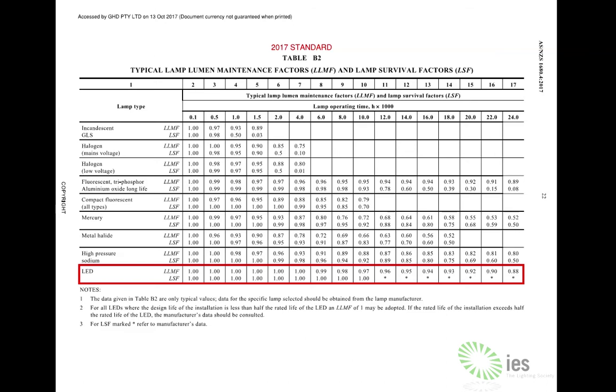It's really strict, and the reason for that is I want to fall back on the ability to compare A and B and say these two are not technically equivalent at any point. The 2,000 lumens, the L70B50 50,000 hours versus the L90B10 100,000 hours completely changes the thing. And as a result, I'm happy to use the L70B50 50,000 hours.